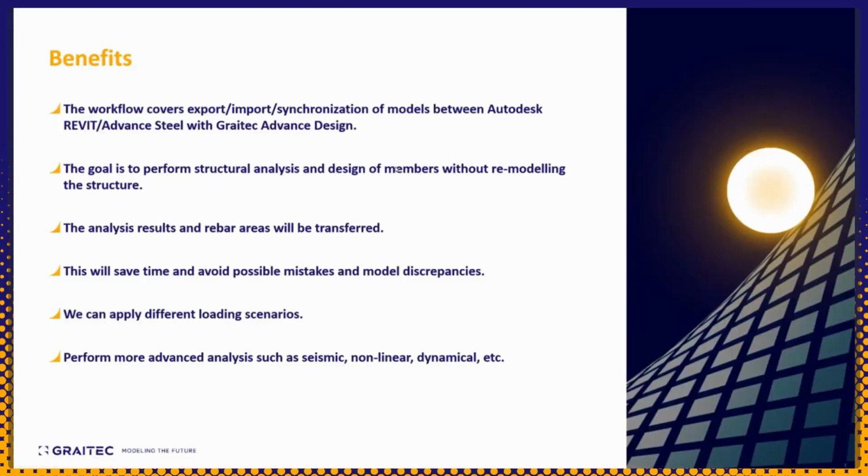Okay, so let's talk about the benefits of this workflow, which is going to be helping you basically to send your models from Revit or even Advanced Steel inside Advanced Design to perform your analysis. As you see here, the workflow covers export, import, and synchronization of models between Revit and Advanced Design. The goal is to perform the structural analysis and design of members without, again, remodeling the structure in your structural analysis solution, in this case, Advanced Design.